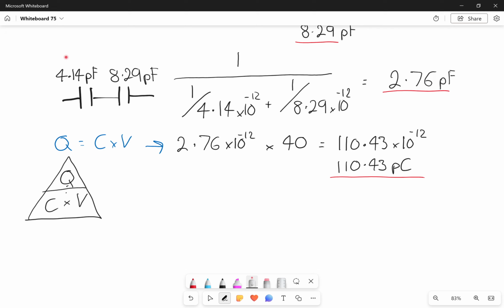Now when we transpose our formula, if we cover up voltage, it prompts us to do charge divided by capacitor value, and we're going to do capacitor number 1. The best way to remember this and write it down is if we want voltage in capacitor number 1, we have to use the value of capacitor number 1. So when we transpose our formula, it will be Q, which is total charge, we've only got one value for that, and it will be C1, because that's our capacitor number 1 that we want to find the voltage across, and that will effectively give us V1.